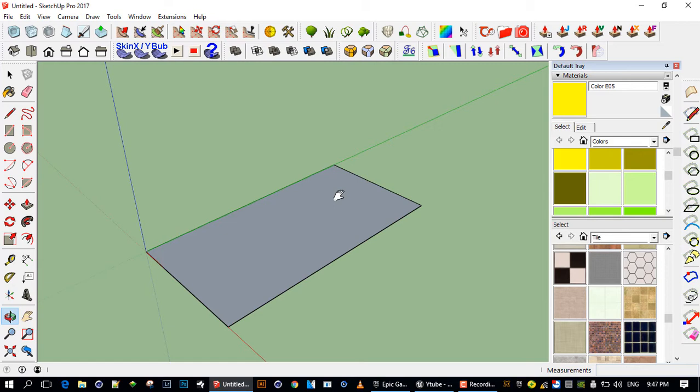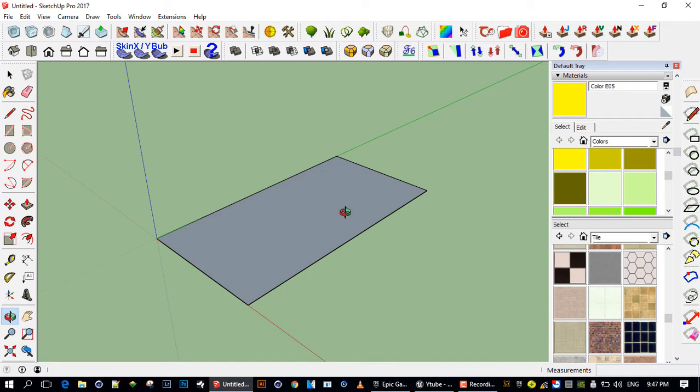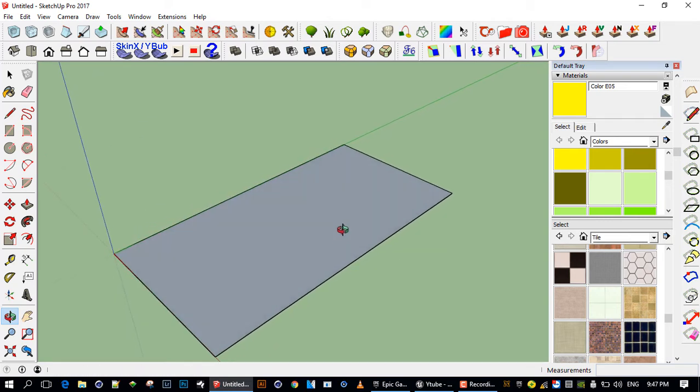I thought that was a problem of SketchUp from the word go, but it's actually not. SketchUp creates a UV map for all its models, and when you import it into Unreal, there's a box you check that says create a second light map UV. So Unreal creates a second UV map, and it lays out the UVs very neatly. The person who can be responsible for messing up the UVs that get into Unreal is the person designing the model in SketchUp. If you follow good guidelines, which I'm not going to discuss here, and create your models well, you're probably not going to have that problem.